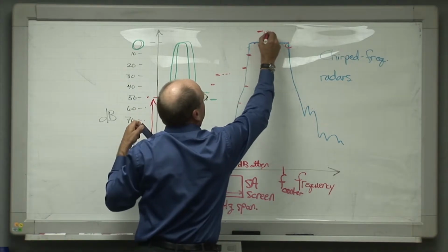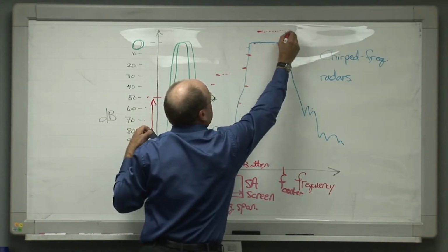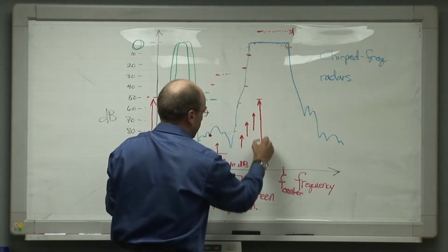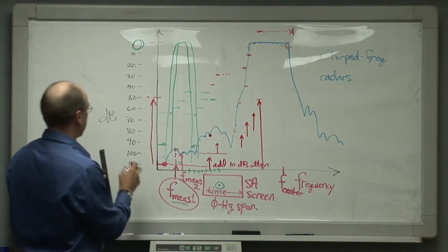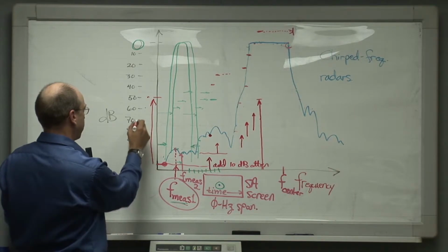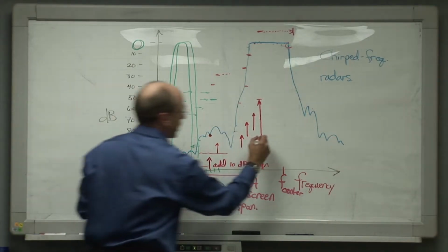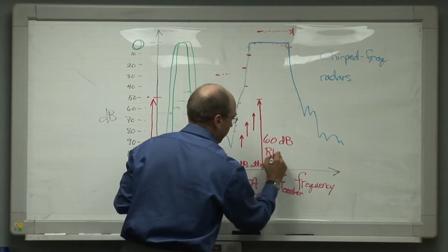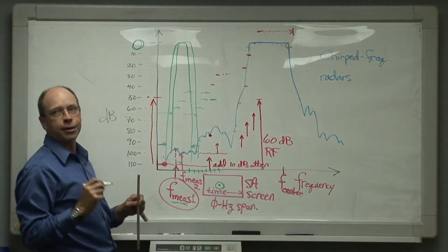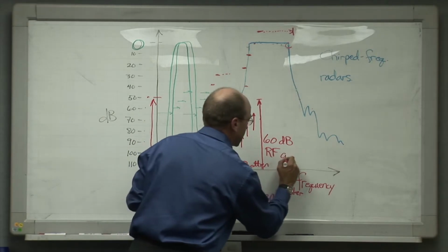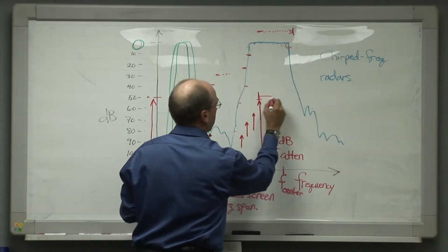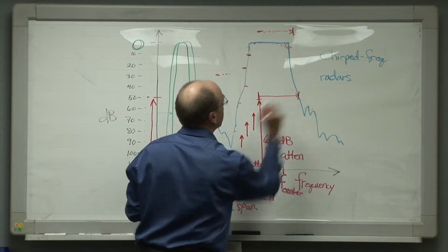And now from this point forward, we walk our way across the spectrum to here with all this attenuation inserted, which the way I've drawn it is in fact 10, 20, 30, 40, 50, 60 dB of RF attenuation. And we actually have 70 dB of RF attenuation in our measurement systems. 60 dB of RF attenuation that we keep in from this point all the way across over to here, basically.